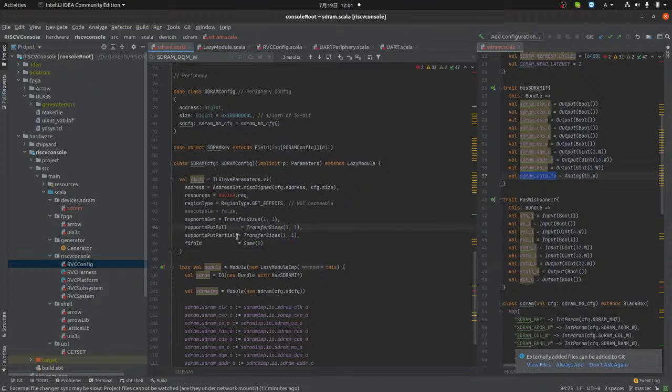Again, transfer sizes, the stuff here, the RISC executable, the region type, the device actually, and the address set that we just put here. So this puts the address set, the address span, which is going to span through address and the size. The reason why it's misaligned is because if we only put an address set, it's expecting a mask. So the misalignment will convert all the address and size with the aligned masking pairs.